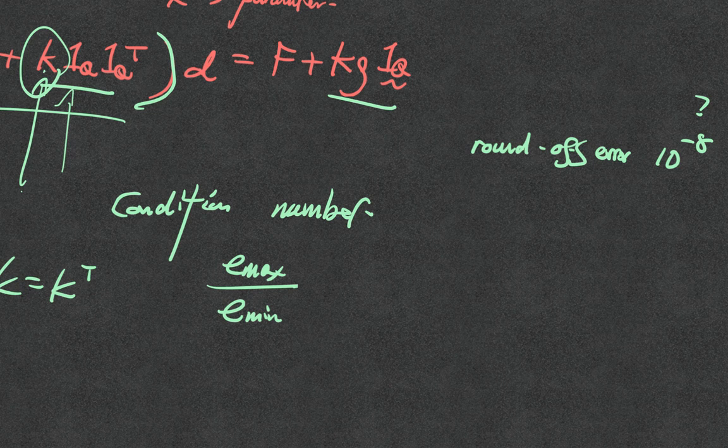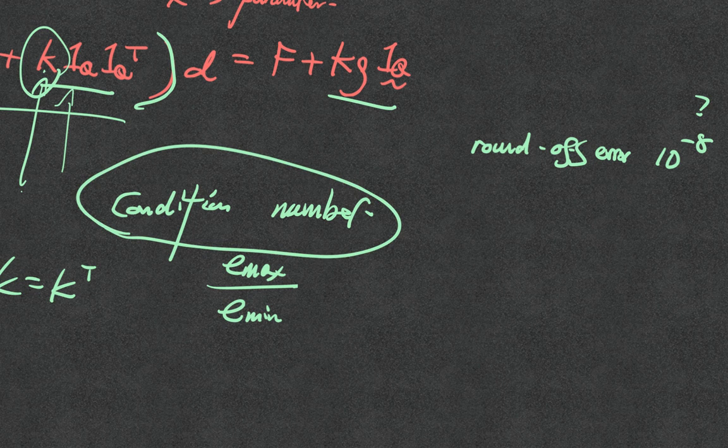So you need to give some room between the round-off error and the condition number, even if you use a non-iterative method like the LU decomposition, which is slower than the iterative solver. I won't talk too much about preconditioners and solvers. Maybe I'll talk about it in a later lecture. But in general, the units you set up matter a lot, and you always want to look out for the condition number. In MATLAB, it is cond of the matrix. Check it before you solve the system. I can give you an example.